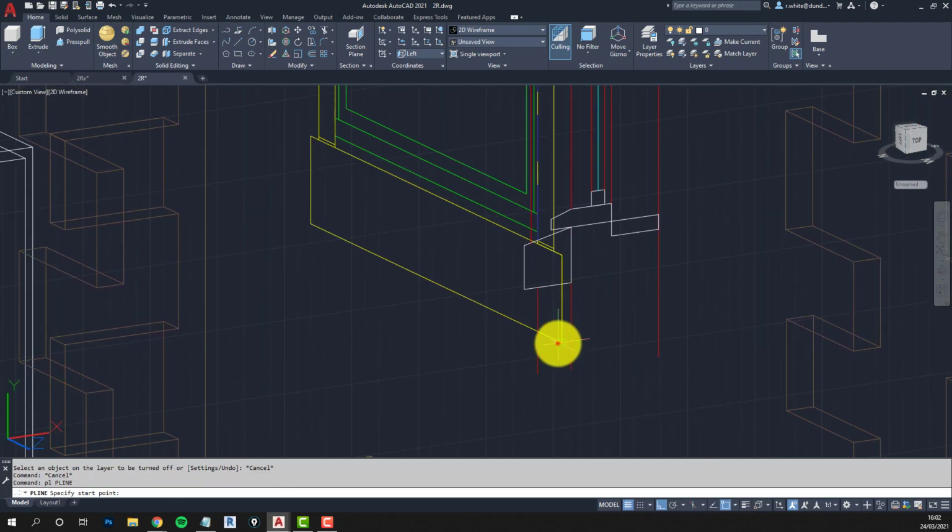Okay, so just like we did before, just a polyline, and polyline down from here. Okay, I should be able to extend that and then trim one with the other, and that's how much I need to stretch just the windowsill. This stays where it is. I'm just stretching the windowsill now. These lines have done their job. Okay, let's just move it to the side so we can delete it afterwards, and then stretch. So S, enter, and I'm going to go by this amount.